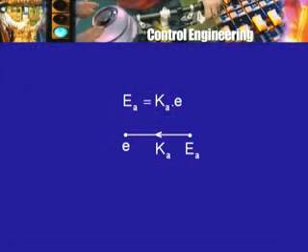This is one equation, but there is one more equation, and what is that equation? That is the equation which represents the motor which drives the generator which feeds the armature, and the generator field current is then controlled, or determined, by this error signal E, and therefore we have simply written armature voltage EA equals KA times E.